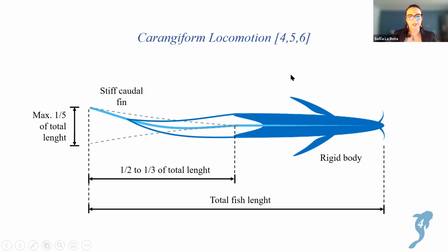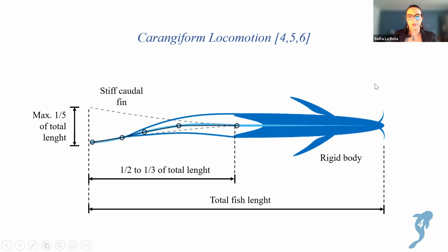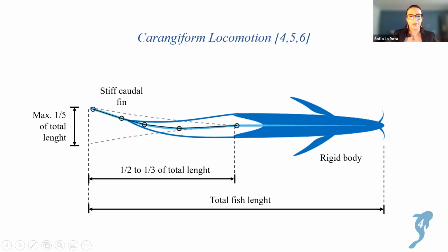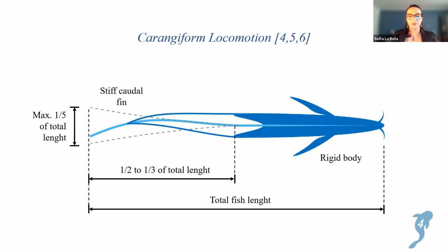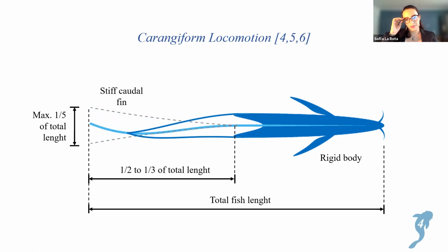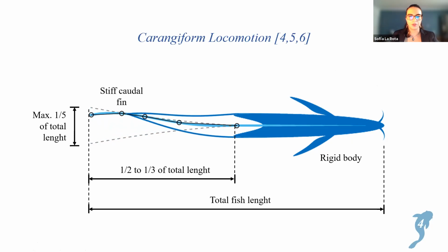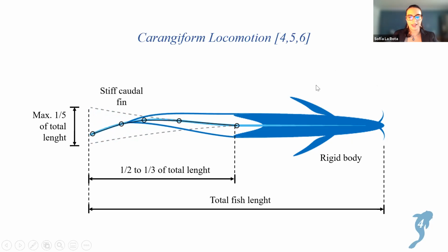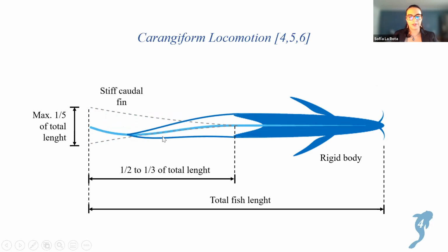The movement is characterized by a more pronounced swishing motion near the caudal tail, which decreases steadily towards a relatively rigid body. The gist of the issue is that there is no standard technique or model to this day that models carangiform locomotion. And even though tail flexibility is thought to play an important and yet poorly understood role, fish tails have often been modeled like a series of rigid propulsive elements.